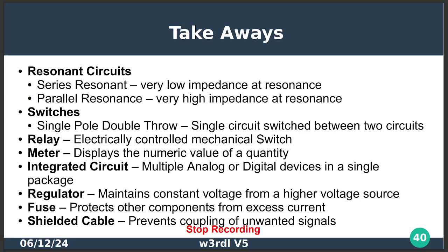Okay, takeaways. Resonant circuits. Series resonant, very low impedance at resonance. Parallel resonance, you have very high impedance at resonance. Switches, single pole, double throw, single circuit switched between 2 other circuits.